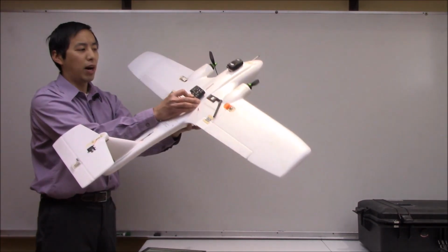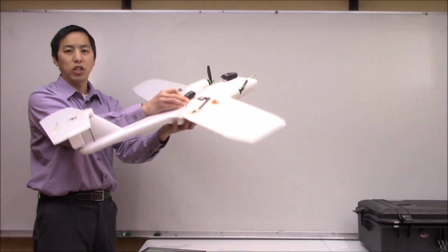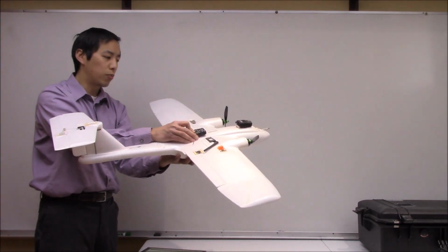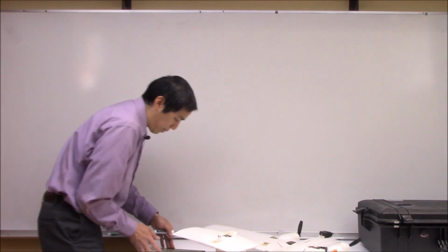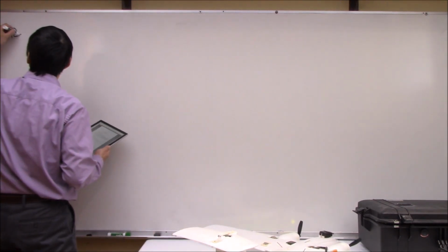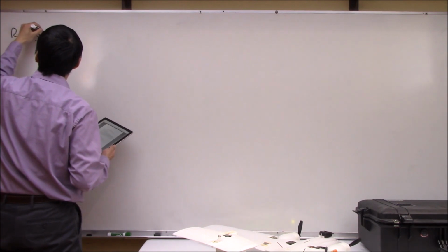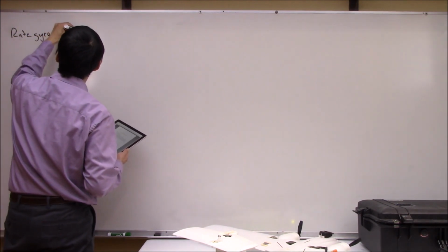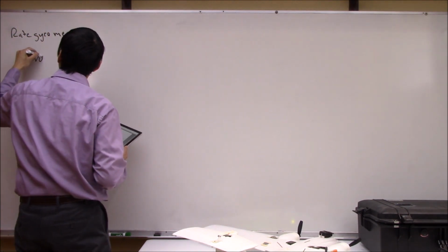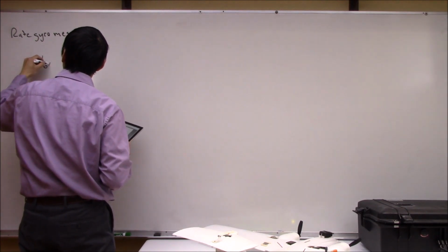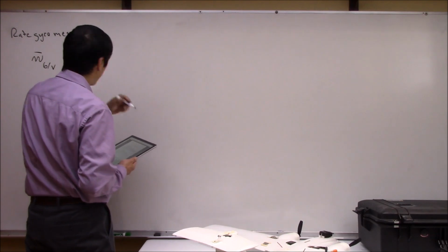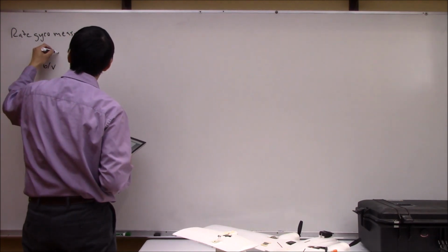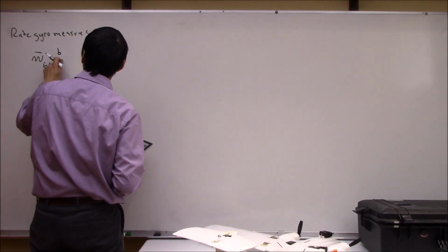So as the body moves around, so does the rate gyro on board your IMU. It measures the rate of the body with respect to the North-East-Down frame, and since it's strapped to the body and probably aligned with the body axes, we can express this in the body frame.